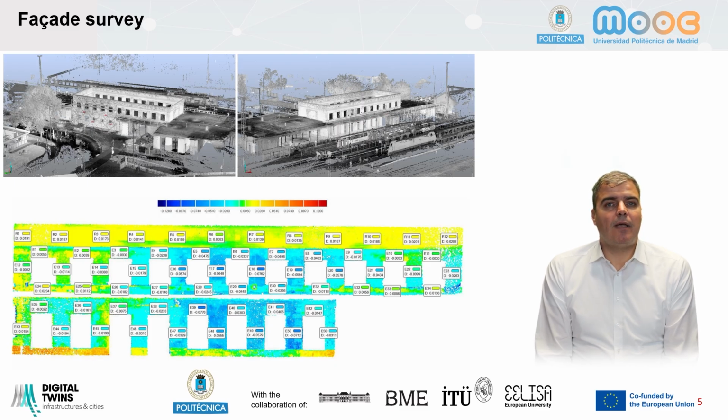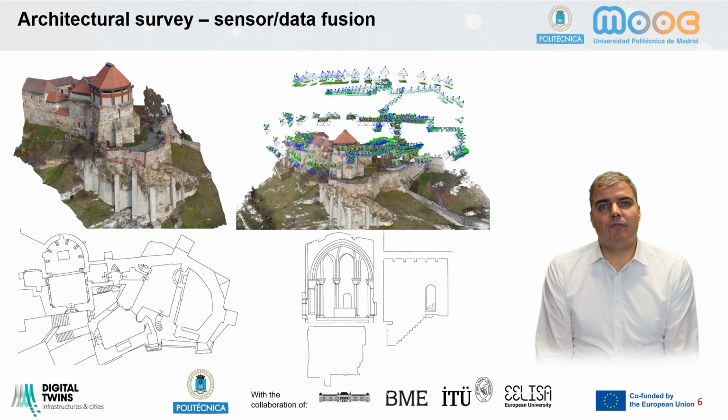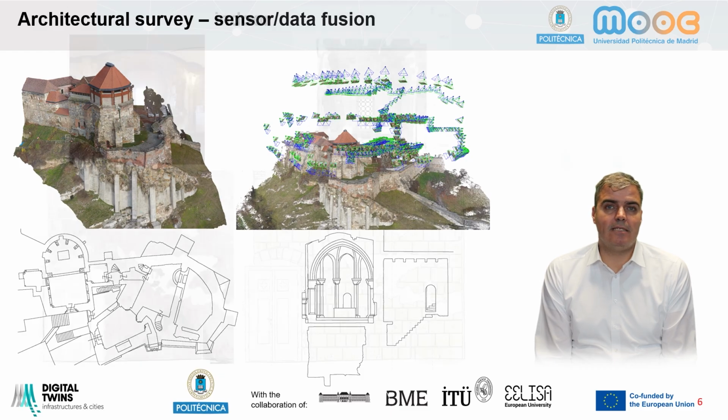This is an example of capturing a building from outside and from inside. And as you see the geometry, there are steep slopes and very tricky distances to capture the outside geometry from terrestrial laser scanning. So therefore, we used photogrammetry. As you see the positions of the UAV images from above, from the air, and we captured the geometry of the building with terrestrial laser scanning and derived 2D products for architectural survey. We also derived orthophotos from inside.